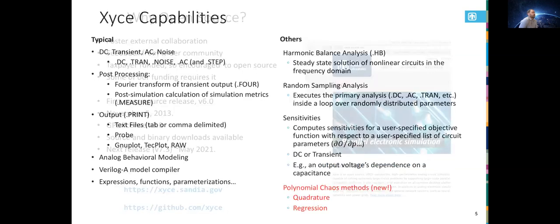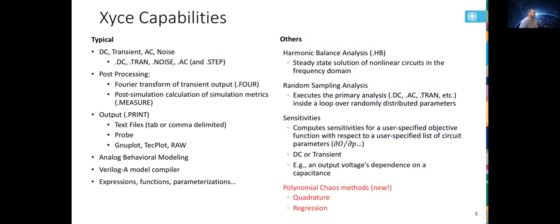Let's see. So just to give a high level view of Xyce's capabilities, like most circuit simulators, there's a lot of standard analysis that we support, including steady state, DC, transient, frequency domain, small signal, AC, noise, etc. And we also support a lot of post-processing options, .measure and .fourier, things like that. We also support a lot of common output and input files. So it's getting, we hope, easier and easier to have Xyce interoperate with other tools. And also we have a lot of support for expressions and also for Verilog models. So that's another aspect of the code that's important.